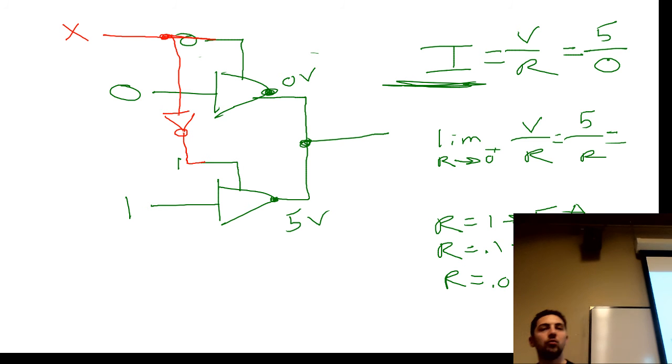So now only one of them will ever be enabled. This is a core principle that we use in larger designs. We have to choose which item gets control over the bus. When we're talking in chapter 4 about devices, remember this idea that with tri-state buffers, we can choose between multiple inputs and send it to a single output.